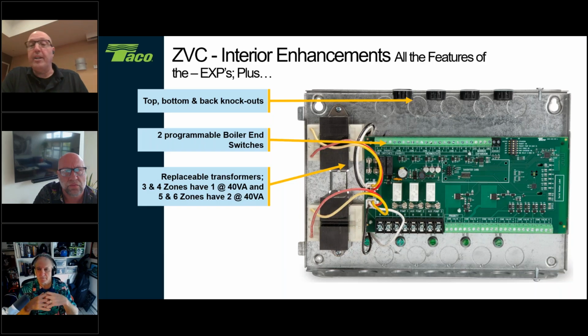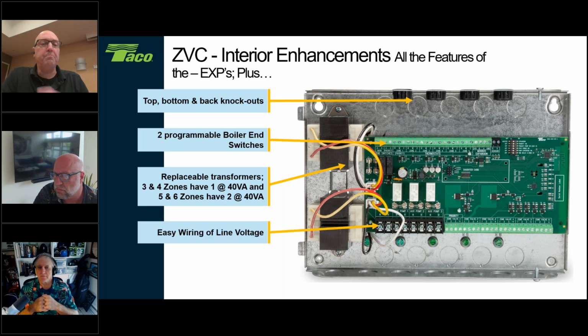Let's say you had a 6-zone system like this and you were using our 571 zone valves, which take a lot of power. You're going to get basic thermostats on there with the 240s, and you're not going to be looking at 6 Wi-Fi style thermostats. So we can help you out with that too.